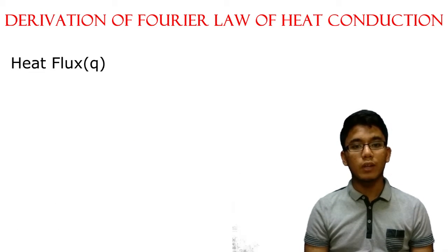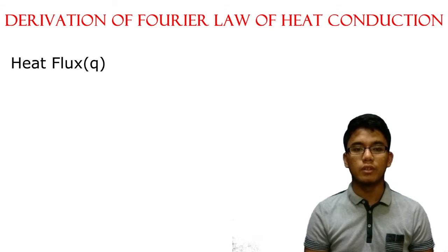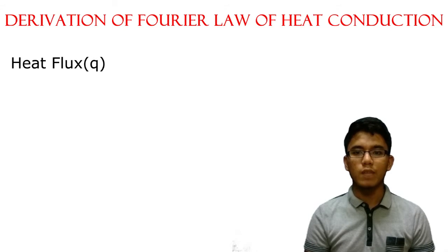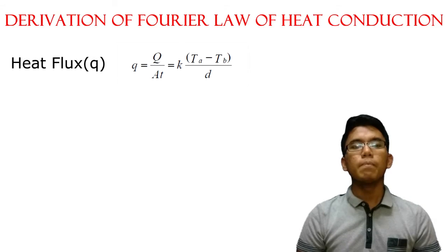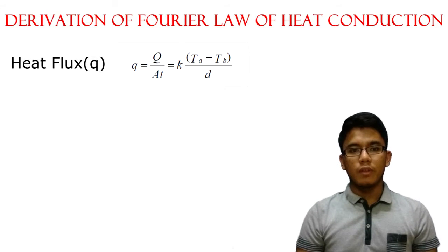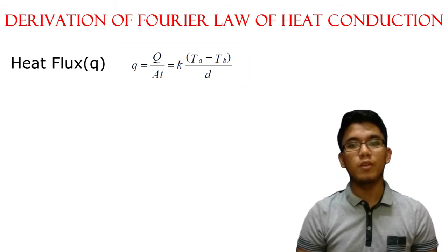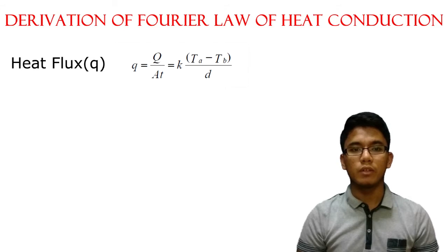Consequently, the heat flux q, the sense of intensity of heat conduction, is used more frequently in engineering analysis. From the previous equation, we may define heat flux as this equation. We realize that the newer equation, that is the heat flux equation, is derived from a situation of heat flow through a thickness of a slab with distinct temperatures at both surfaces.